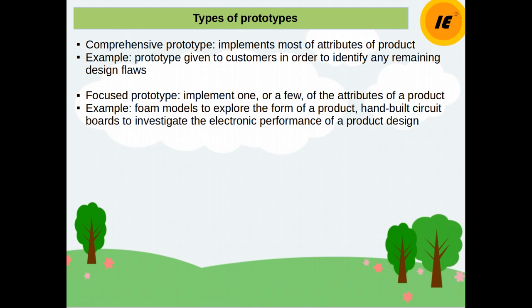One of these prototypes is often a look-alike prototype, and the other is a works-like prototype. By building two separate focused prototypes, the team may be able to answer its questions much earlier than if it had to create one integrated comprehensive prototype. So works-like means from a functional point of view, whether the robotic arm will work in a desired way or not, and whether it can maneuver in rough terrain or not.